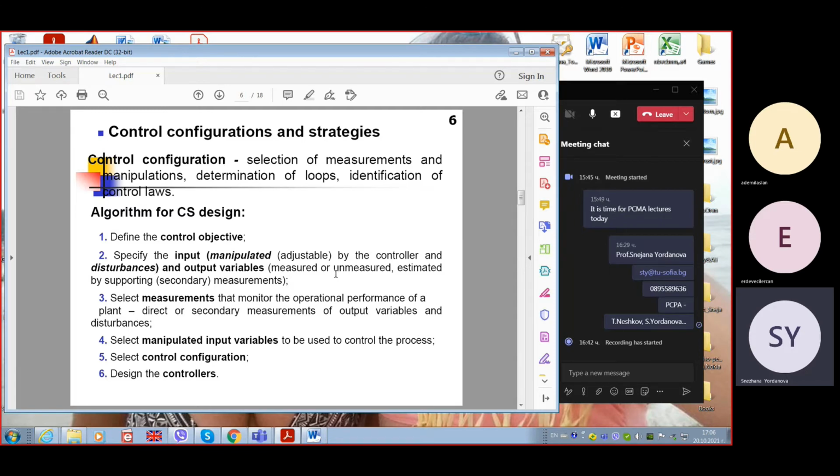Thus, it's a physical law that creates voltage based on the temperature difference between the cold and the hot junction. So the free ends are the cold junction. The hot is the one inserted in the medium, the connection between the two metals.